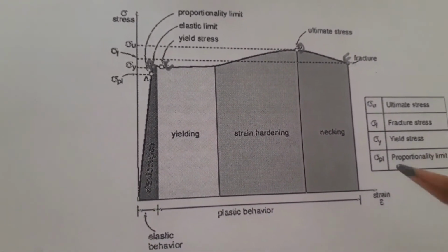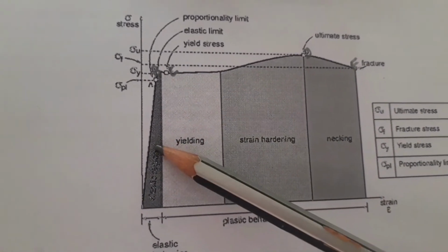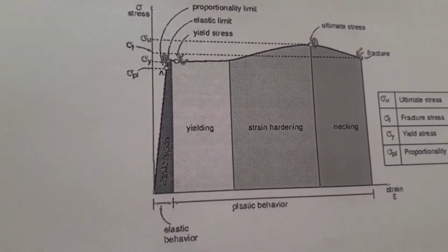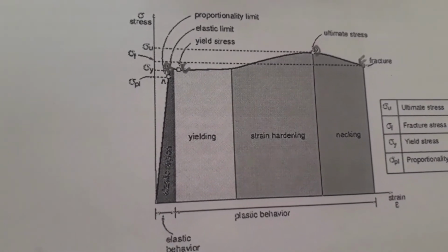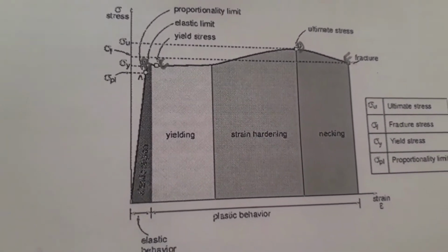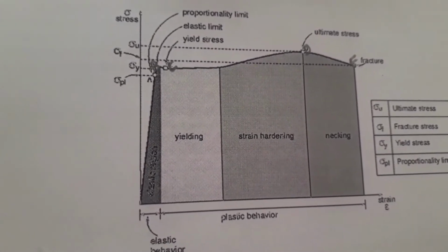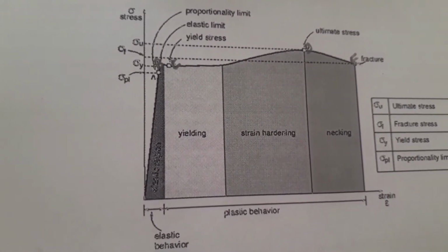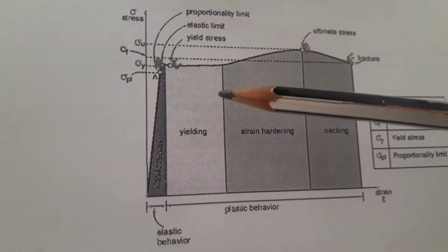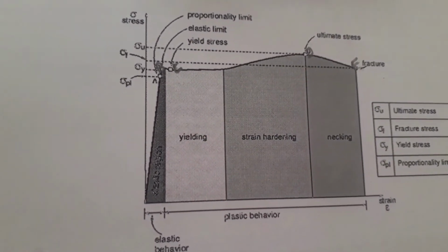So elastic deformation is represented by the capital A. This is the first phase of the stress strain diagram, elastic deformation. Already you know very well, elastic deformation means once the load is applied on that material, it changes its position. After release of load, again it comes to its original position. That is called elastic deformation. When the stress acting on the material is removed, the material regains its original length. This is called the complete recovery or resilience.